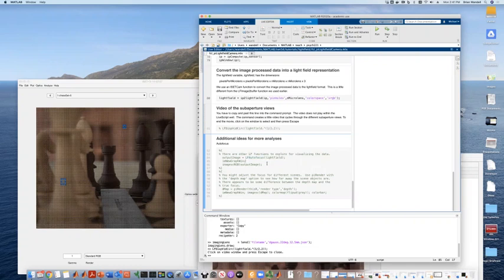So people could play around with the number of pixels underneath the micro lens, and see how much information that gives you for autofocusing, and also for changing focus, and also for estimating depth. I guess you could play around with the exposure duration to see the effect of noise. That's true. And then the lens design: the distance between the micro lens and the sensor, the size of the micro lens, the curvature of the micro lens. And the nice thing about this is that because you're using PBRT, you have depth information, so you actually know the real depth.